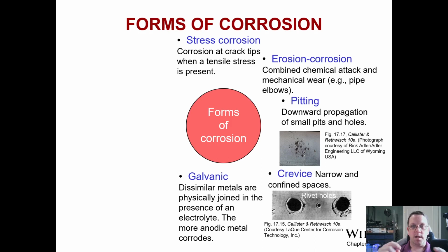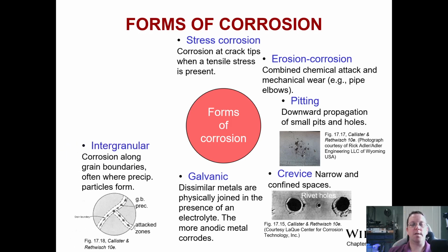But the galvanic pairing allows for liquid that creates an electrolytic path in order for the metals to exchange ions. Just like in the example of that hydrogen electrode, and looking at the examples of that battery type arrangement, you have the pairing where you have dissimilar standard potentials creating a path for galvanic interaction.